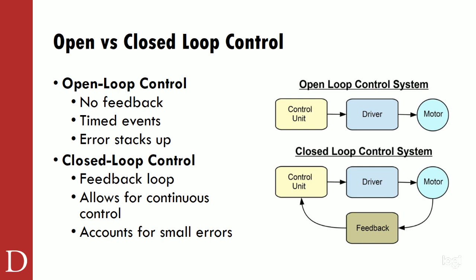I might set my set point to 57 to be able to maintain 55 miles an hour going uphill. But I might set my set point to 50 to maintain 55 miles an hour going downhill. So that's the benefit of closed loop.